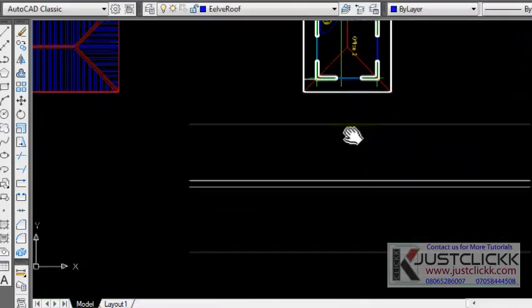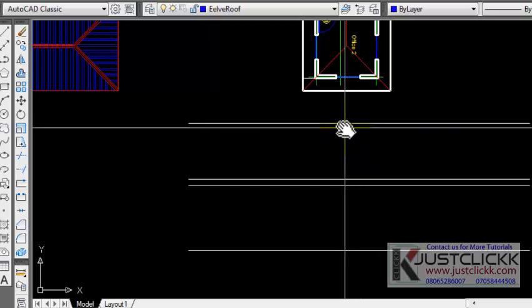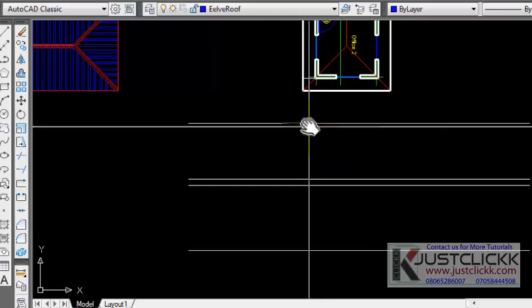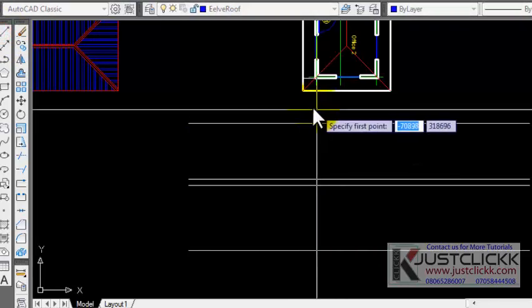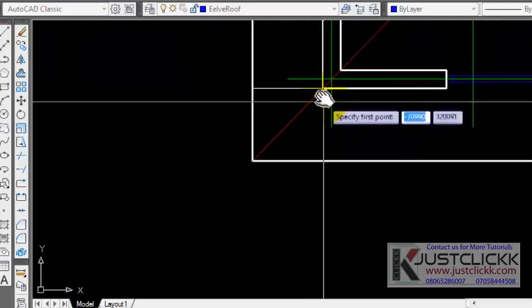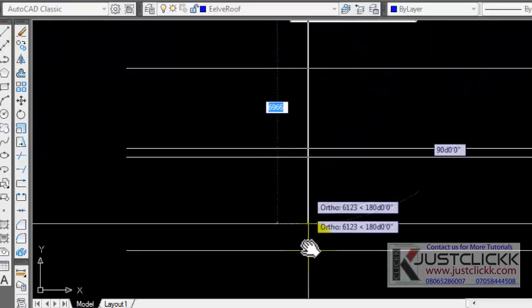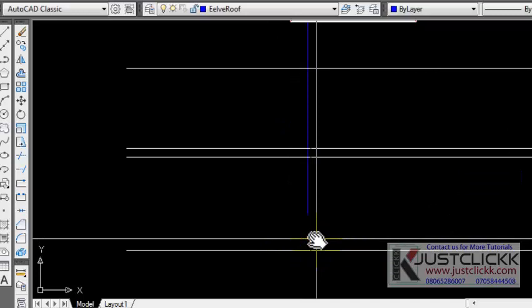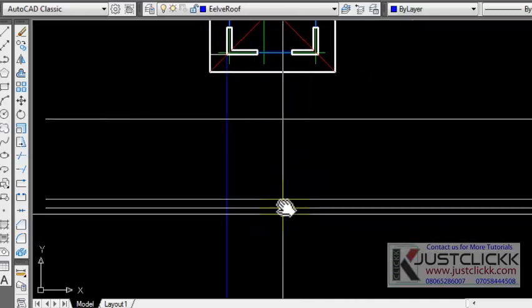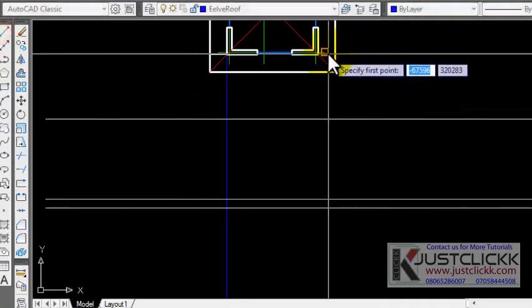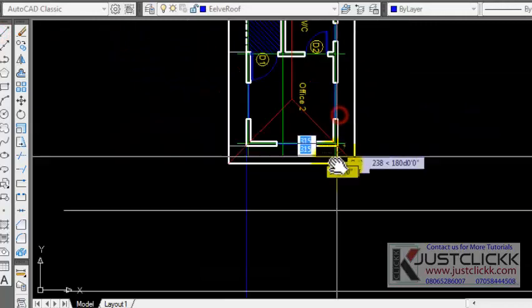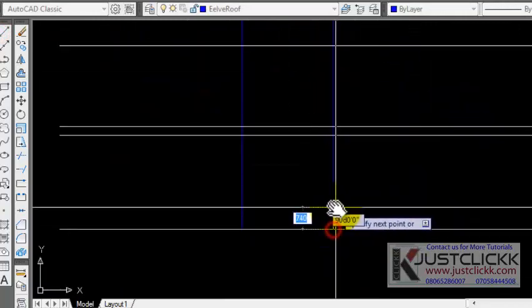Alright, so now you will begin to use the same technique we used in creating the front elevation. Pick the line tool and then get the external walls, like this, straight down to the surface. Create external walls like this, straight down to the surface.